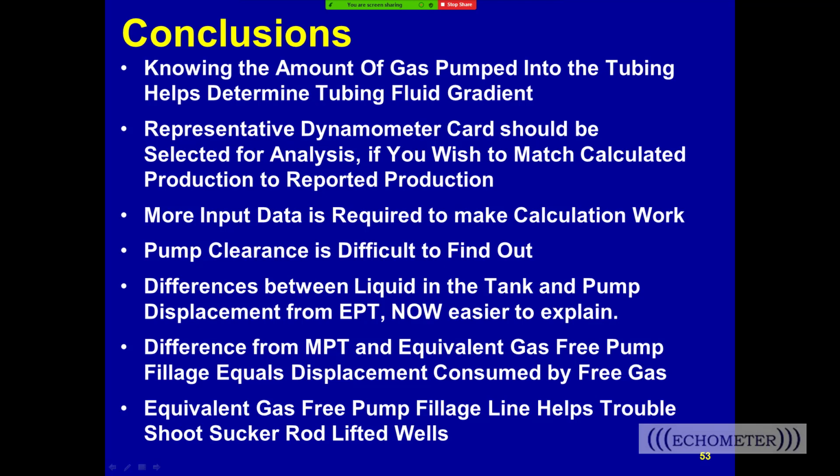Now, the other thing that can cause it to be wavy is if you have your rod string upside down. When you type the rod string into TAM, if the rod string's upside down, it makes the pump card wavy. If the rod string's entered in incorrectly, it affects the wave equation that models the behavior of the rod string. And so if the rod string that it models isn't what's in the well, then that'll make the pump card wavy. So the first thing I usually check is this rod string entered in, is it input correctly?